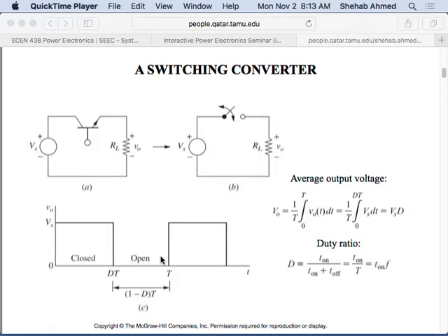It's a topic that is quite interesting. But basically, what it says is there are reflected waves, depending on the shape of the waveform and the length of the cable. There will be some reflections of the waveform that you are sending. So if I am sending a pulse that is 1 kilovolt, by the time it goes and comes back, if I'm sending another one, at some point this pulse is going to be twice the value, right? So basically the long cables will distort the waveform. It's a big discussion about the transmission line phenomena, but the idea is they distort the waveform shape.